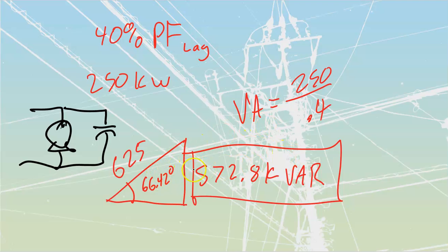The danger in doing this type of power factor correction is that if I put in this amount of vars C, so I've got this vars L, and I match it with a vars C, and then something happens to this load, either my vars L decrease, it gets more efficient somehow, or my watts, the amount of true power, decreases, it's going to change what I have. And I'm going to have too many vars C at that point, which means that I'm going to go into a leading power factor, an overcorrected power factor. Overcorrected power factors are always going to be bad. They lead to an increased terminal voltage on a transformer. So we just want to try and avoid that. We'll examine some stuff for that later on.